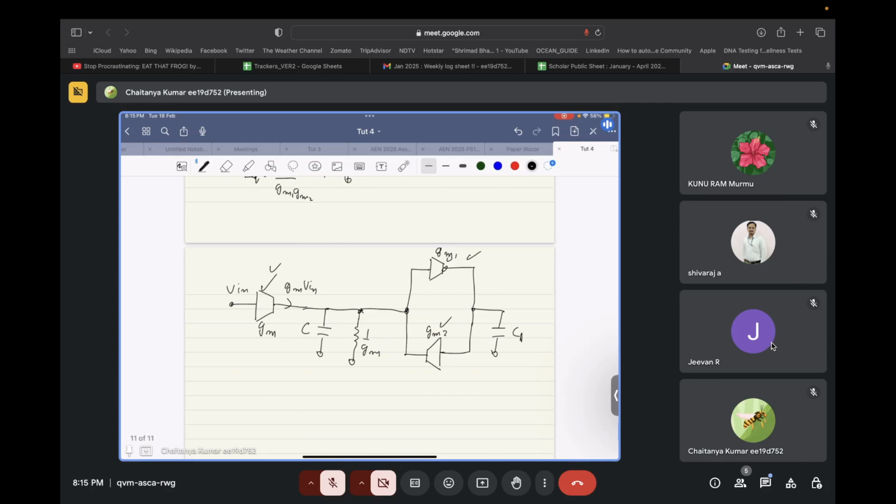Generally one kind of component changes in a certain way. So if all of these are changing in a certain way and this resistor is changing in some other way, then your transfer function will become corrupt. Maybe your bandwidth will change, or your center frequency will change, and you can't do anything about it because you will have to keep track of so many different kinds of components. So generally in an integrated circuit, it is preferable that you have similar kinds of components.